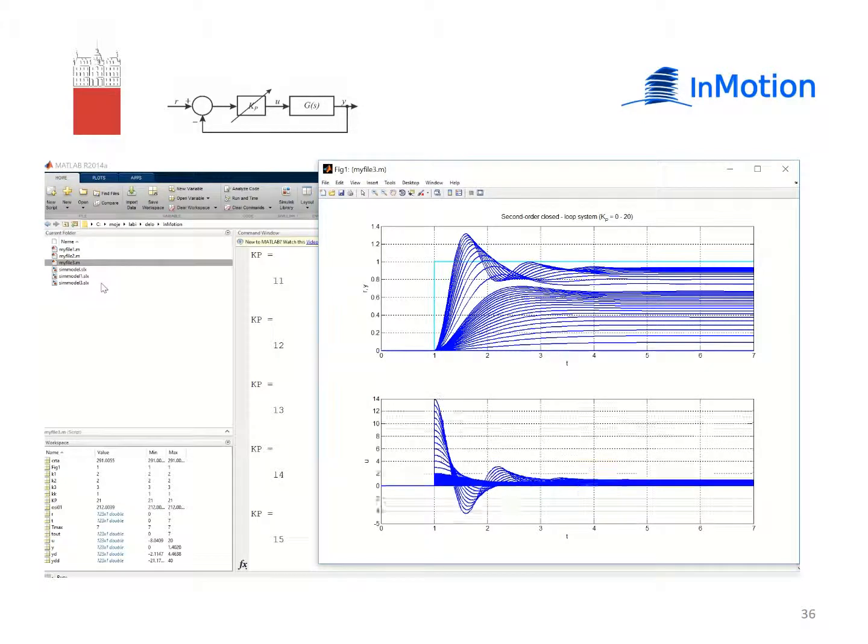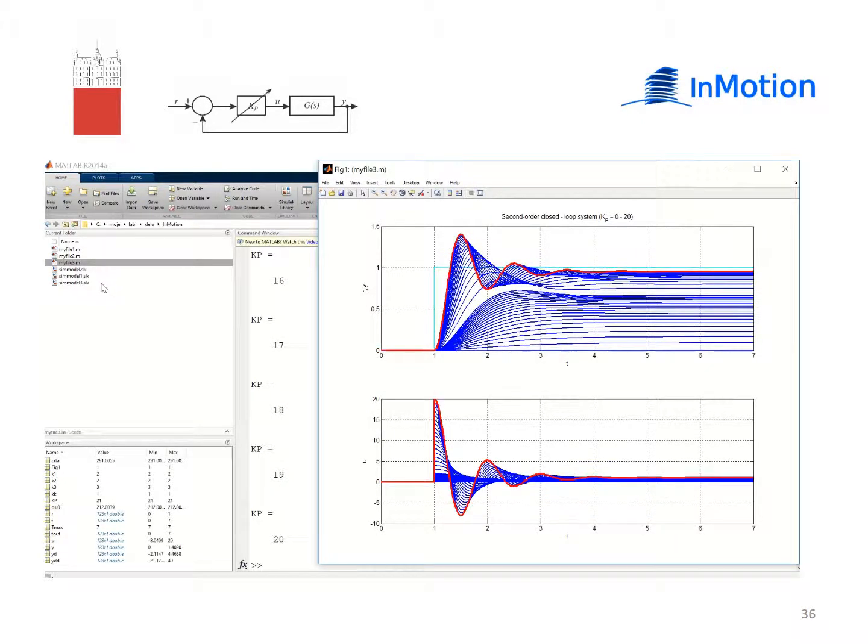It is obvious that for the smaller values of Kp, the closed-loop system is overdamped, while later on the overshoots to the step input signals are increasing. This means that the system has become underdamped. From this, it is possible also to conclude that when Kp is increasing, the imaginary parts of closed-loop poles are also increasing.